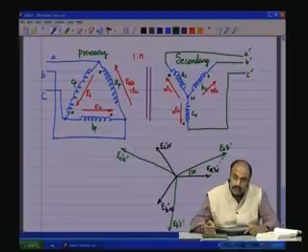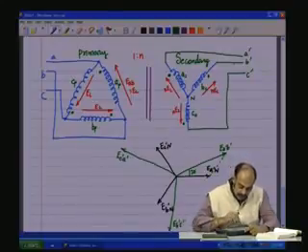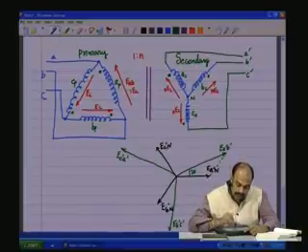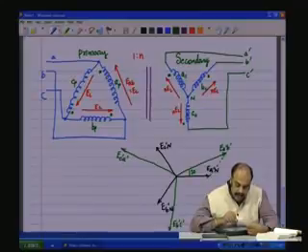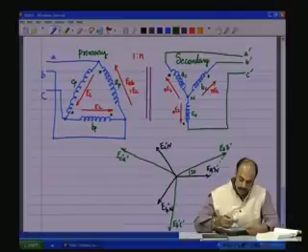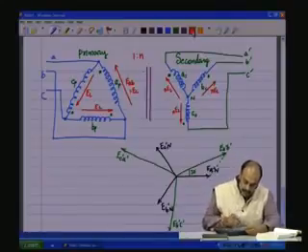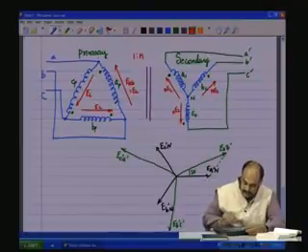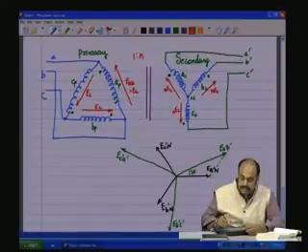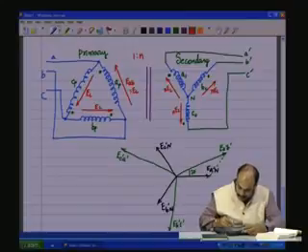Now, if we look at the primary side, there is an exact one-to-one, in-phase relationship between the voltage across A P and the voltage across A S, because of the dot polarity. Okay. So, on the primary side, the phase voltage A P is along A dash N dash.